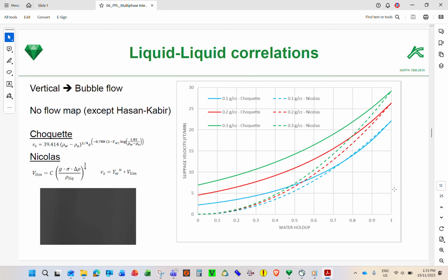Yeah, you can calculate. But of course, it's just the bubbles passing through the needle. As you see, the needle is very small, and you have only 4 needles in, for example, a 7 inch or 5 inch tubing or casing. So we miss quite a lot. Hopefully they are mixed. If they are not mixing, then we miss them, and our calculation may not be correct. It's an underestimate.